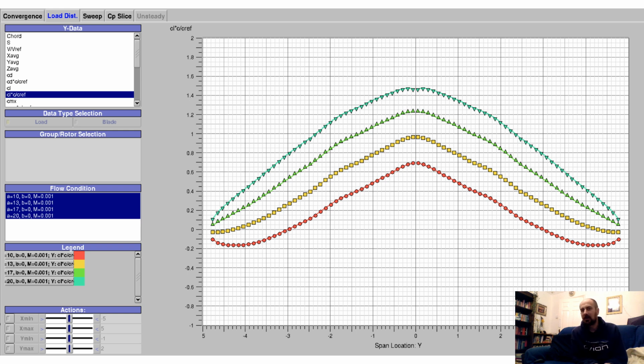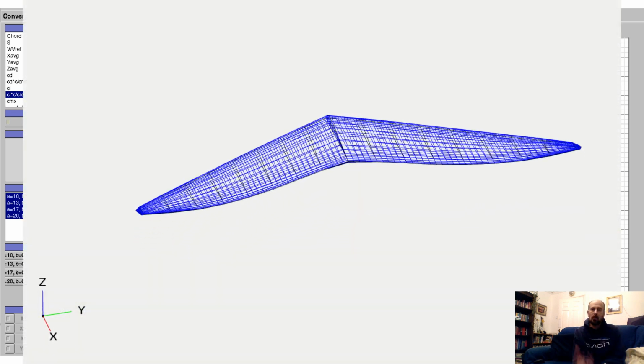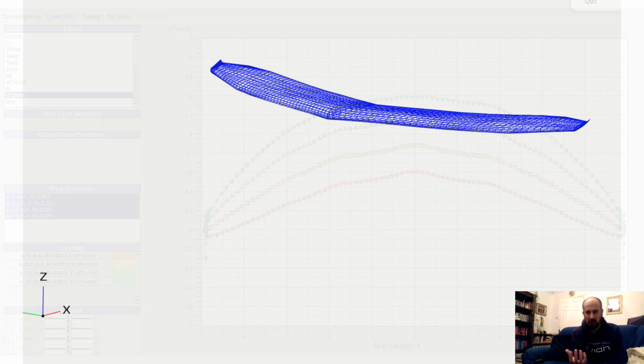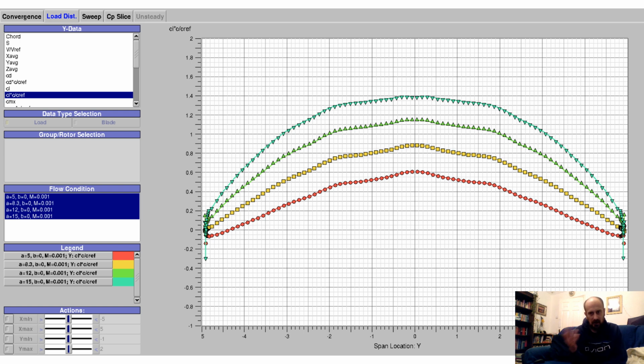In fact, you can see even at the very lowest angles of attack, so the highest speeds, the tips would be generating downforce in this case. So maybe not enough to make the sidewires go slack, but it's a wing which isn't working optimally. With the VG tight, you can see it is better, which is, of course, exactly what you'd expect, because we know pulling the VG tight gives you more performance, and clearly it's a lot more optimal in terms of the lift distribution.